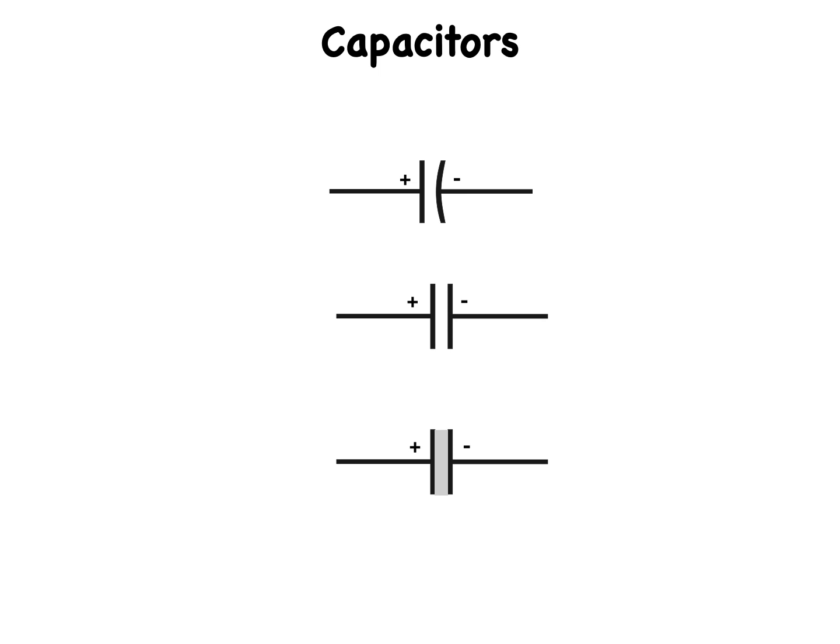You must take care to connect them so that any DC voltage that happens to appear across them has the correct polarity. Most types of capacitors contain only 2 leads, although every now and then, you'll come across one with 3 or more leads. The basic capacitor symbol consists of a vertical line followed by a space, and then a parenthesis-like symbol, or another vertical line. Horizontal lines connect to the centers of the vertical lines or the parenthesis to indicate the component leads.